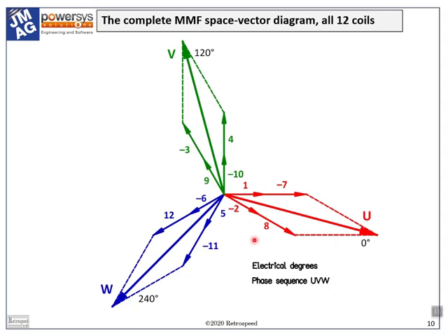This is the right thing to do, however we set it up, because the essential operation of any AC machine centers on just one space harmonic, the one we call the working harmonic. In this case, it's the fifth mechanical harmonic, but sometimes we refer to it as the fundamental on the grounds that it is the first electrical harmonic.